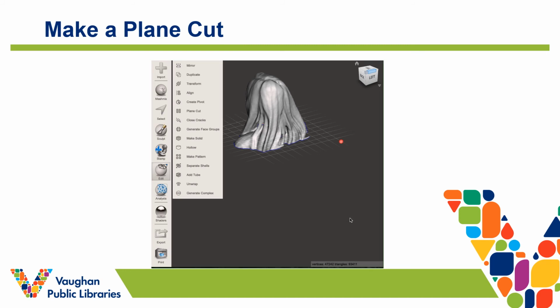The next tool we are going to use within the Edit toolbar is the Plane Cut. This will be a great tool to use to split 3D files into multiple parts if you need to do so for printing. For example, if your item is too large for one single print job. What we'll use it for here is to give the bottom of the scan a fresh, even, and straight cut. So let's first click on the Edit toolbar and then Plane Cut.